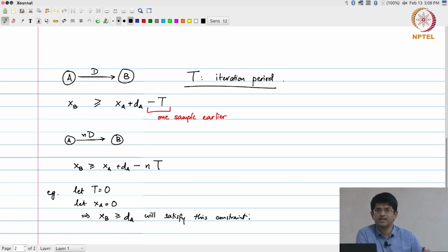But this is what we are ultimately trying to do, and if you think of it in the context of actual implementation of the data flow graph, what we are interested in is, number one, the dA, dB, etc. are given to us along with the data flow graph, so that tells us what needs to be implemented and what are the hardware complexities, the amount of time that will be required for each of these blocks to execute. We are interested in computing a value for t, that is the minimum iteration period under which this system can get executed, and we then want to find out what are possible values for xa, xb, etc., which will allow us to successfully actually execute this on hardware, right.